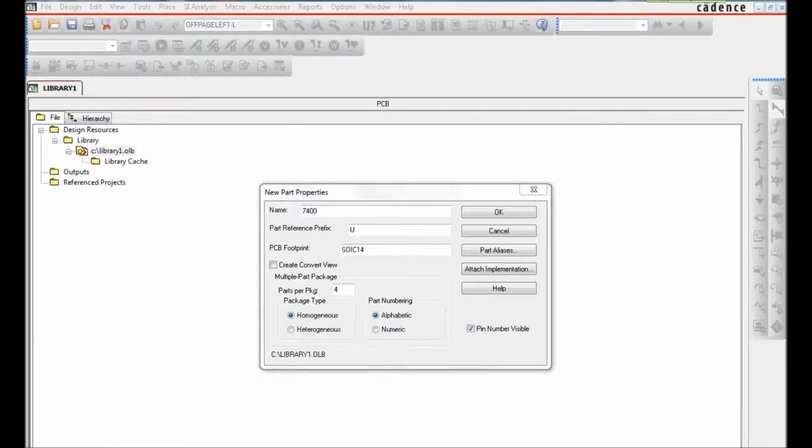So a little bit about this dialog box that pops up. You have Name. That specifies the part's name. This is used as a default part value when the part is placed on the schematic page. Part names can be up to 31 characters long, for example, R1206, RN55.